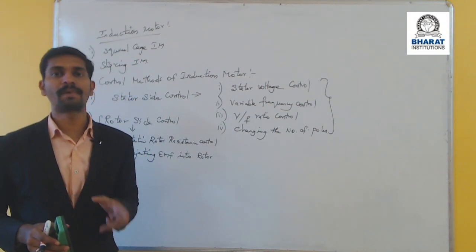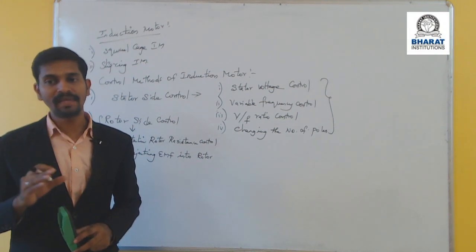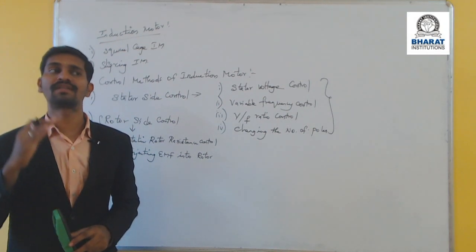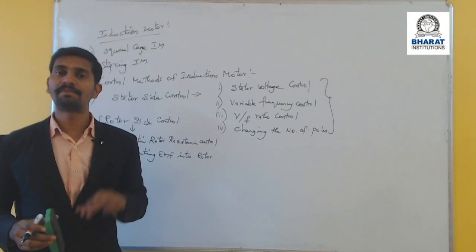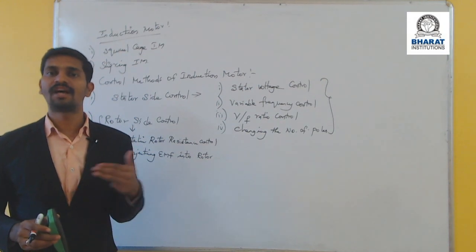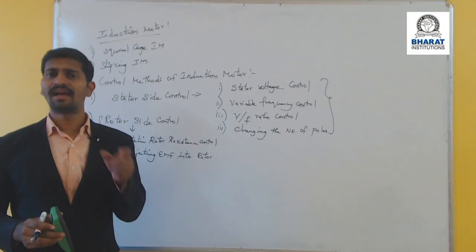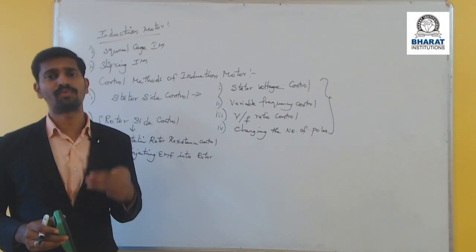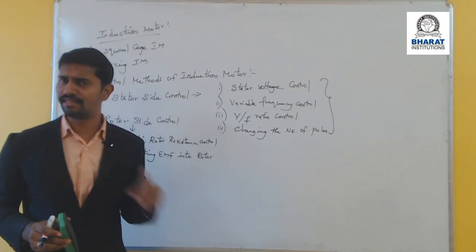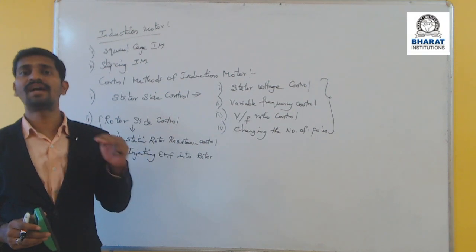There is no problem of sparking with respect to the induction motor. But when we are talking about the DC motors, there will be a sparking problem. So that's why we can't use the DC motors for any type of environment, because it will create some problem, that is sparking leads to damaging the windings, and it requires more maintenance and it is costlier. So that's why nowadays the induction motors are most widely used for the variable speed drive applications with the help of power electronic devices. So next methodology is how to control the speed of the induction motor.